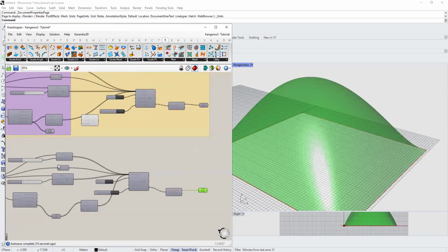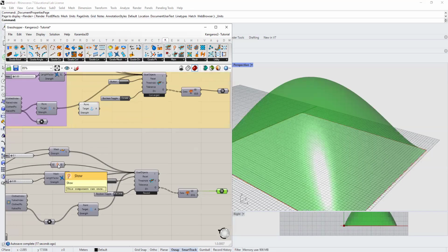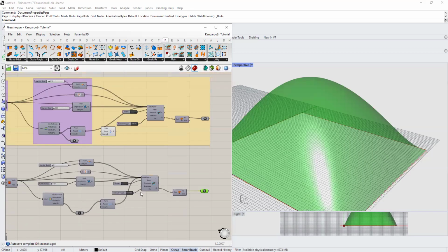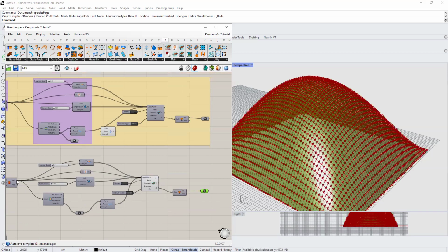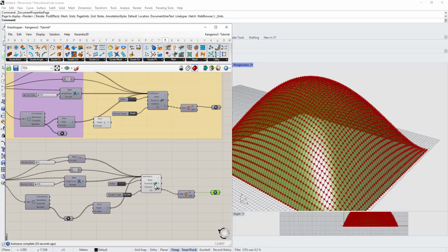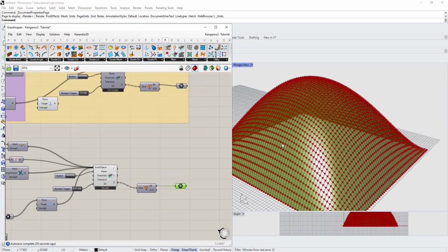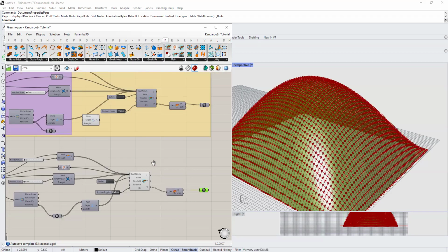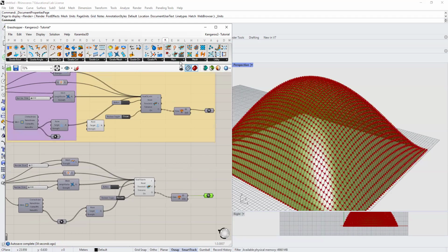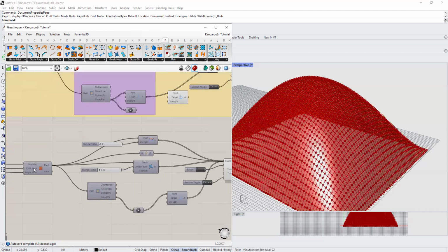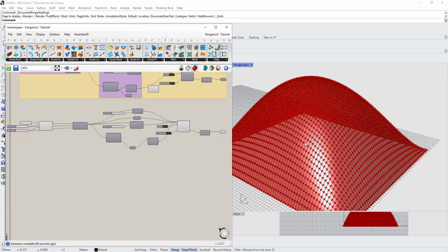The functionality of this show is kind of tricky because you expect that I connected a mesh and then I should get the result. But what you get is just the condition of vertices and lines and not a mesh. So to get the effect of that mesh, you should use this show, which I believe is a component that lets you trace what is happening onto this mesh.